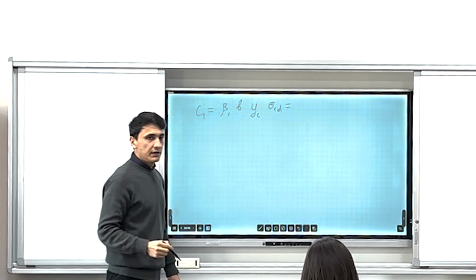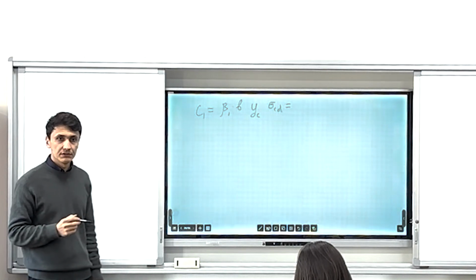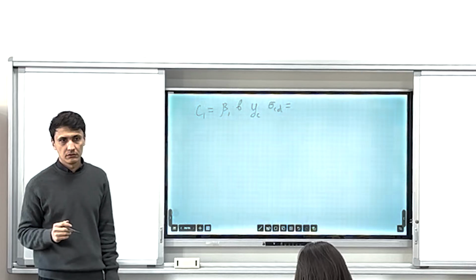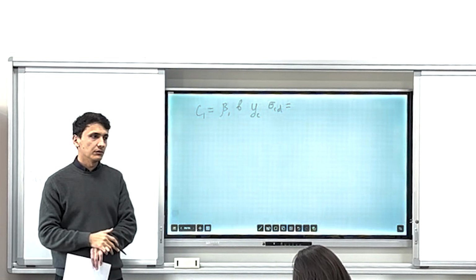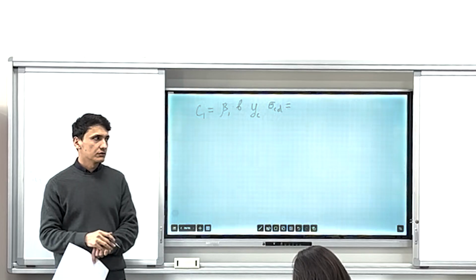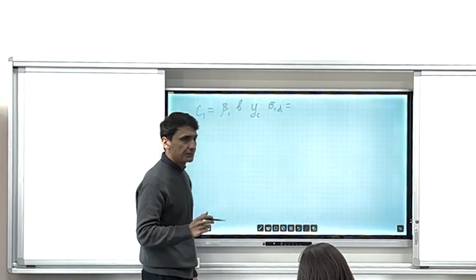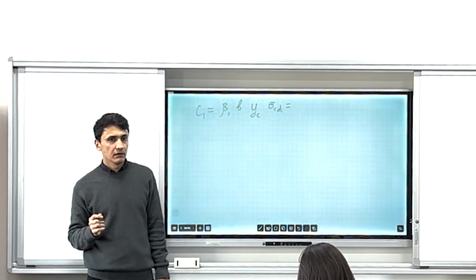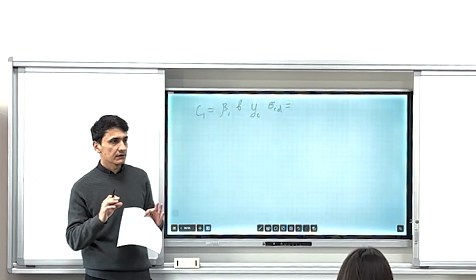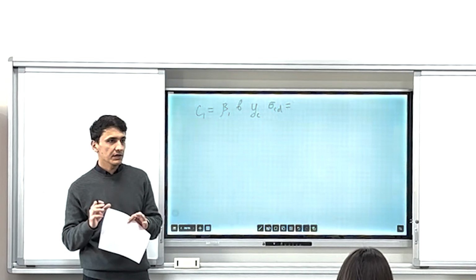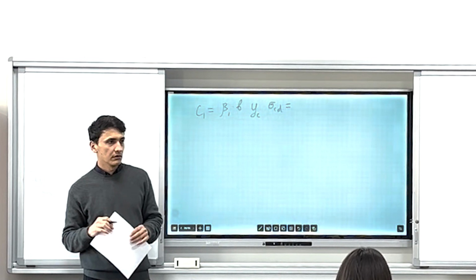So now you have the beta 1 coefficient here. Beta 1 is taken from the Eurocode, but it's not given directly by the Eurocode or any other code. It is derived from the stress-strain law for the compressed part of the concrete, by integrating the stress-strain law.